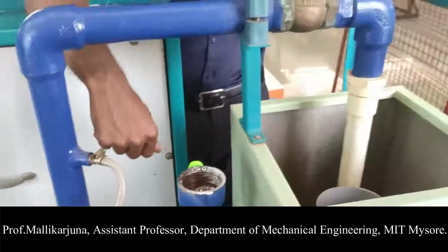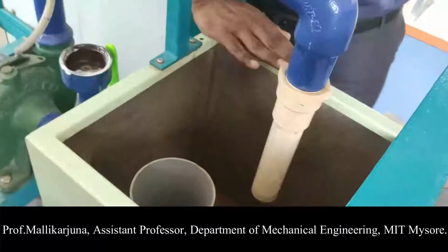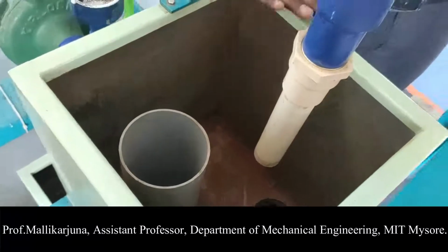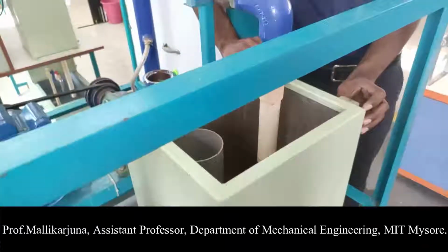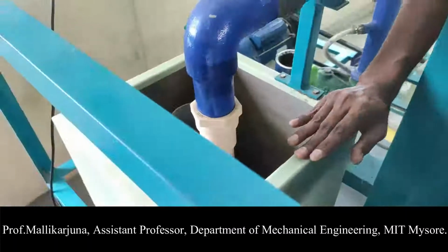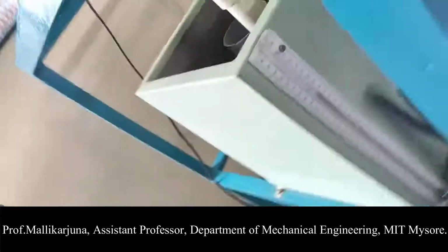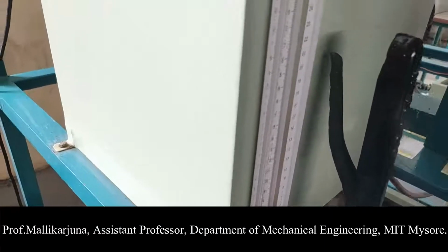Now let us look onto this. This is the collecting tank, which is actually used in order to measure the actual discharge. On the other side, we have a scale over here. With the help of the scale, we need to look onto the actual discharge that is happening through the centrifugal pump. So this is the scale which is provided on the collecting tank.